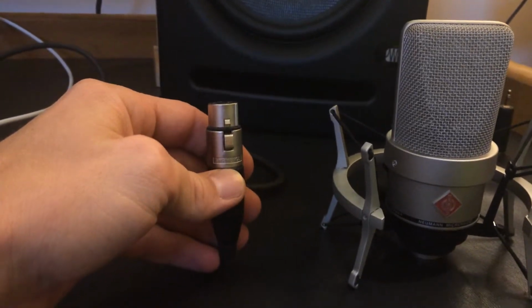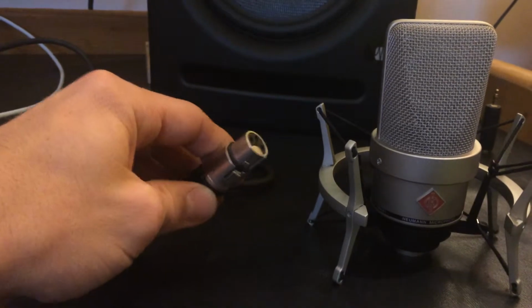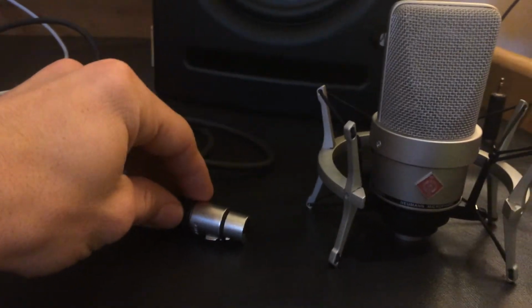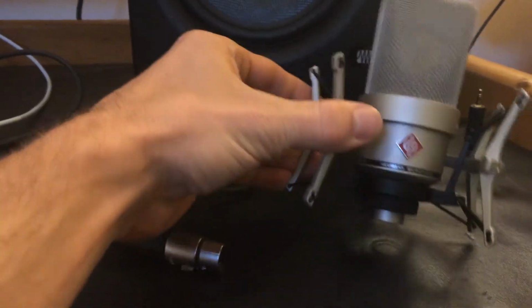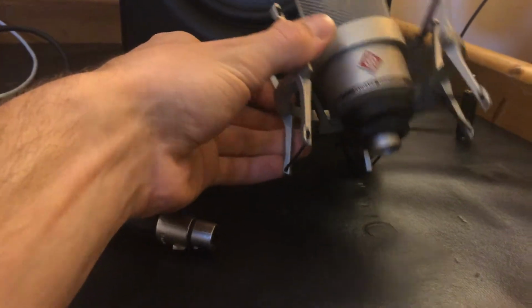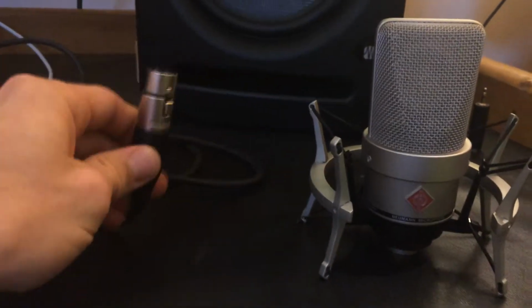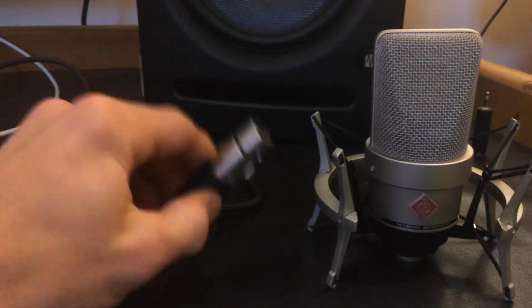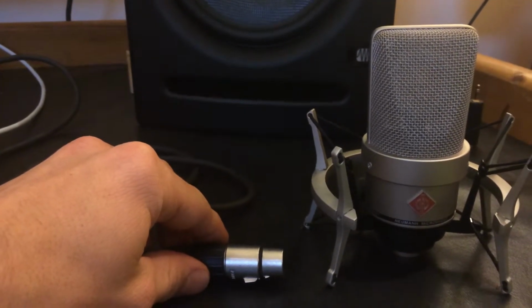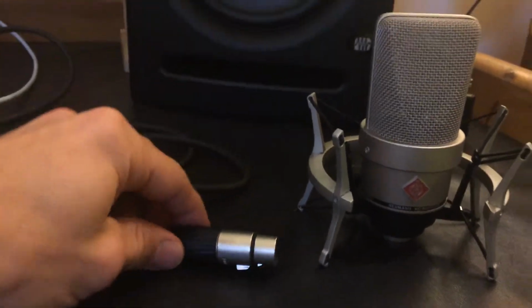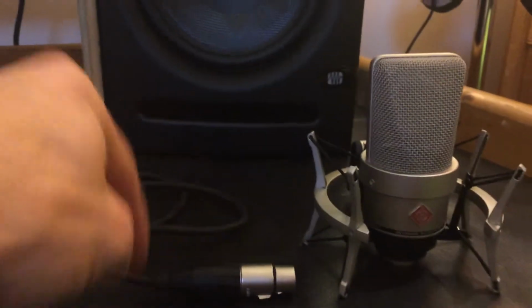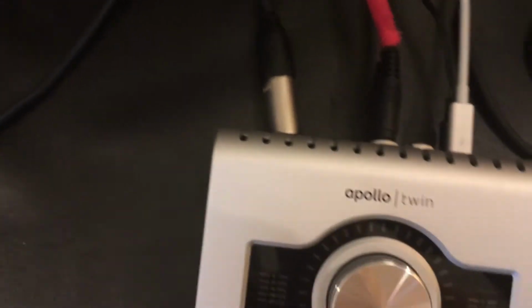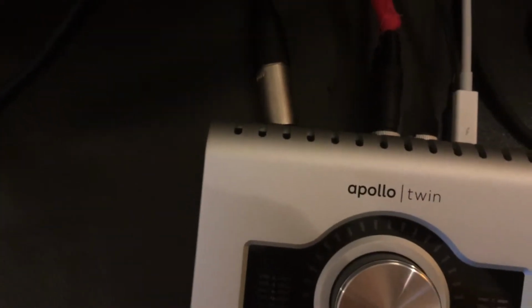I like the way that it was explained in the video. It's called a mic. It's a male, so you got to make sure that you connect the female end of the XLR cable to the bottom of the microphone. So that audio signal travels out of the bottom of the microphone through this XLR cable into the back of my interface. The first place it goes in the interface is the preamp.